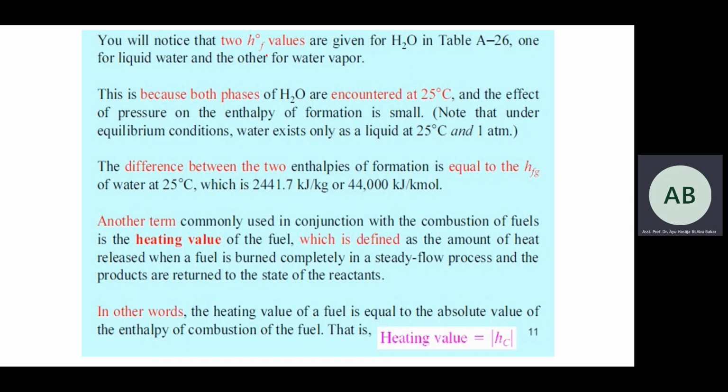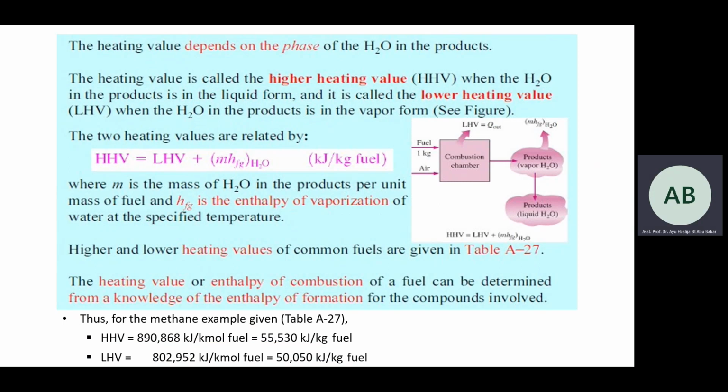Okay, here it mentioned the two values of HF of water. You have liquid and vapor. The difference between the two enthalpies is equal to HFG, liquid minus vapor. Okay, you will get HFG. Another term is defined as heating value. For this one, the heating value is called the higher heating value, HHV.